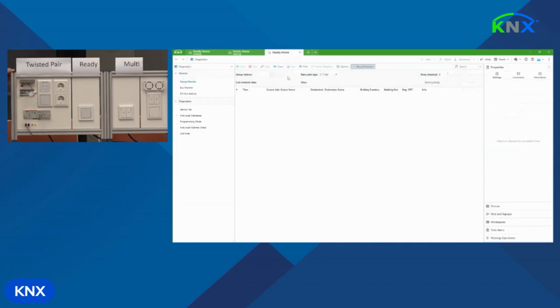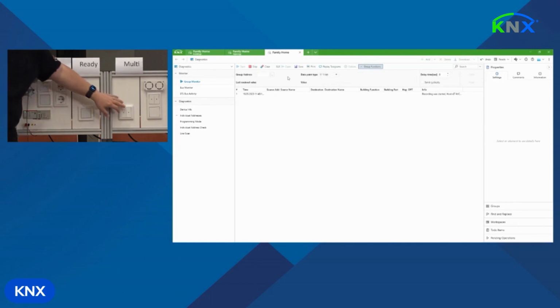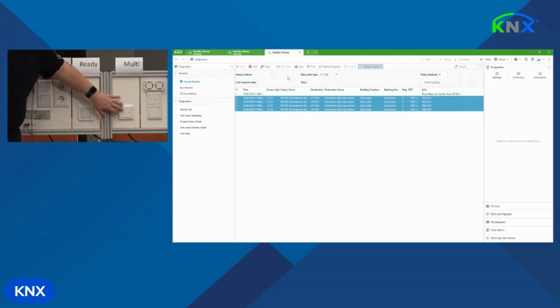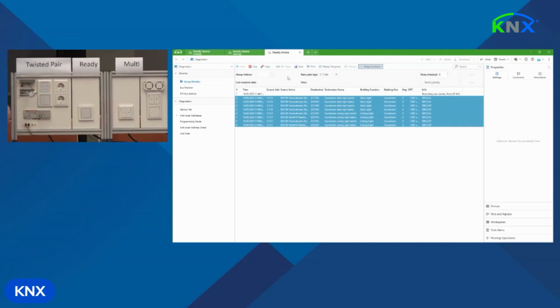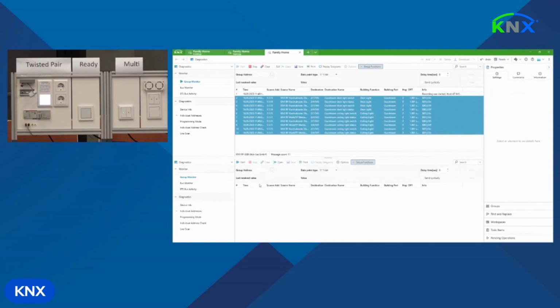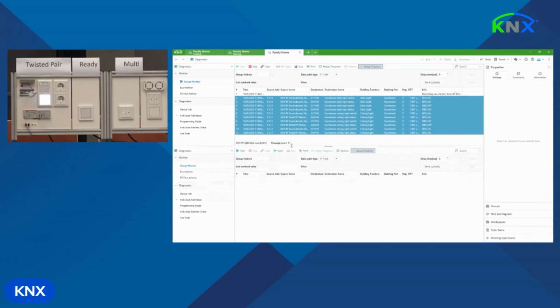after everything is programmed correctly, that not only the communication to the multi-actuator is secured, but also the radio frequency communication to the, I'm not sure if everybody saw this, to the twisted pair actuator. You can maybe open up another panel with diagnostics to see at the same time what's happening on the air and on twisted pair. So if you select in the second panel a twisted pair interface and start this. And it is connected already.